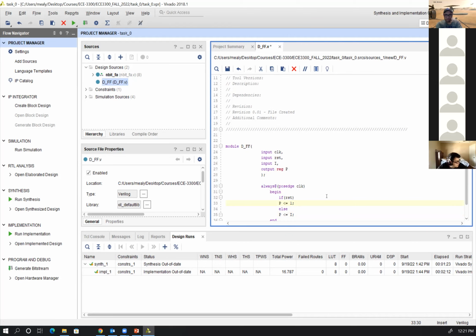Or I can write it differently. I can just make it like 1'd0. Make it decimal, but still 1 bit. You know what I mean? Or make it octal, so 0. Make it hex, 0. Do you see what I'm doing or not?